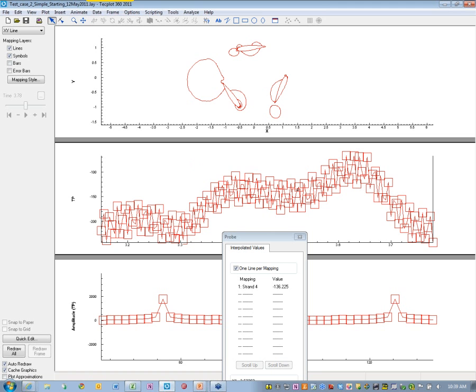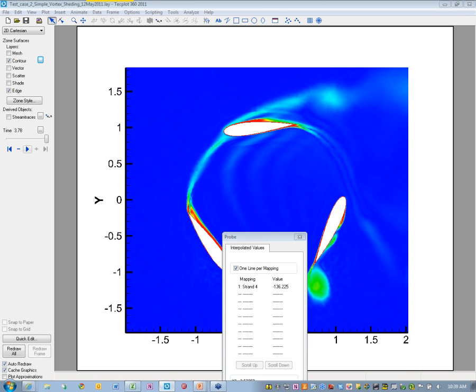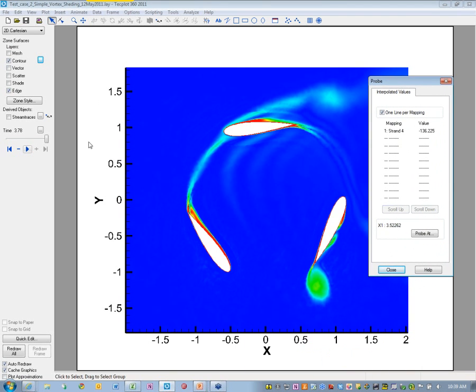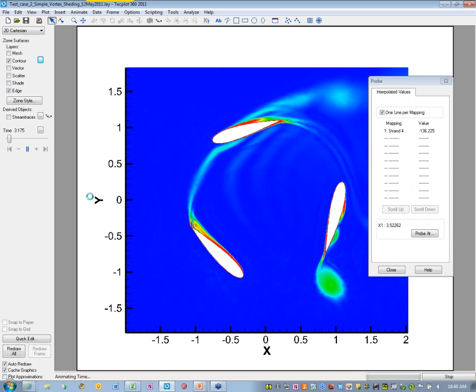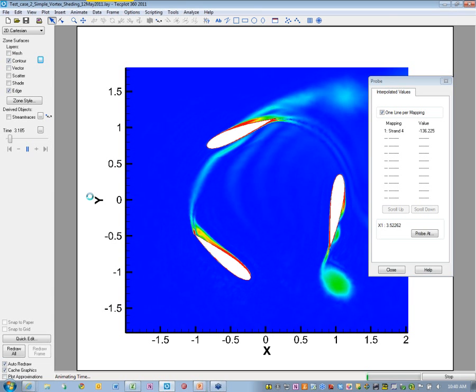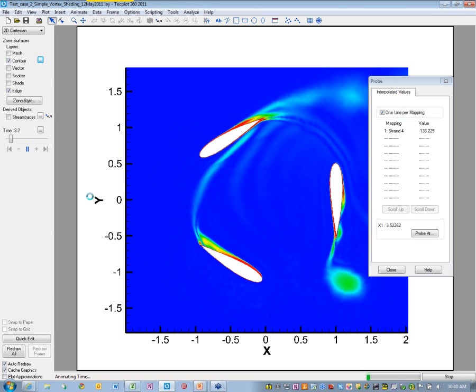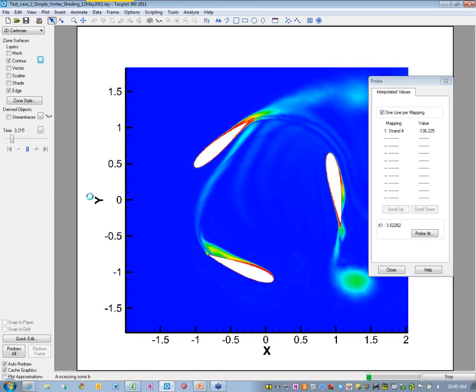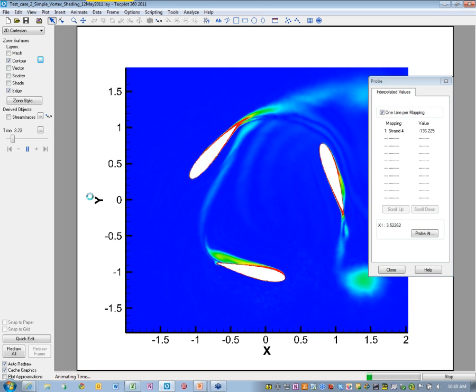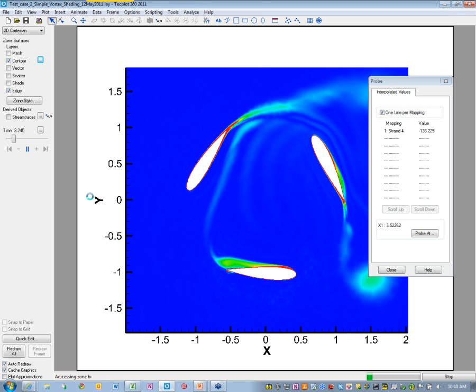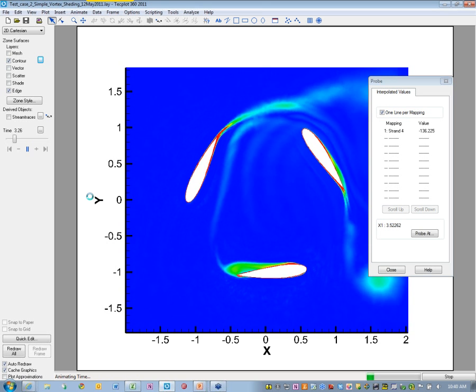So in fact, it really is a discrete Fourier transform. So now I'm going to shift gears a little bit and talk about how one looks at, say, the vorticity. We talked about some integrated quantities, but we'll look at the qualitative information as well. We're going to look at that same model, and now you're looking at the vortex shedding. One of the key things to point out is that this is the optimized design, and I'll show in a moment what makes this design better than the original, I think it was a NACA 5 airfoil.